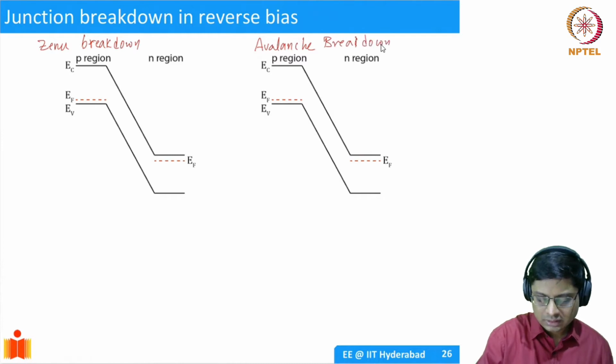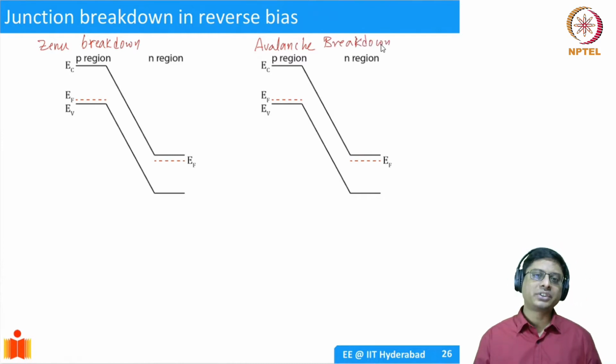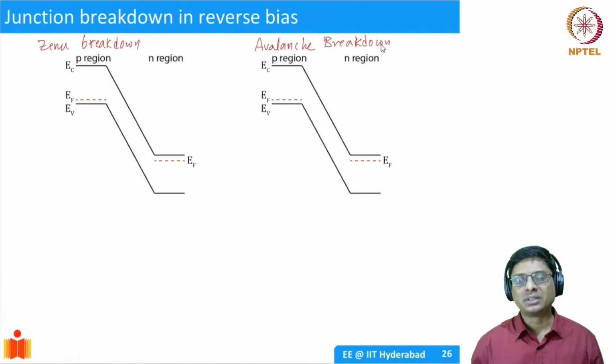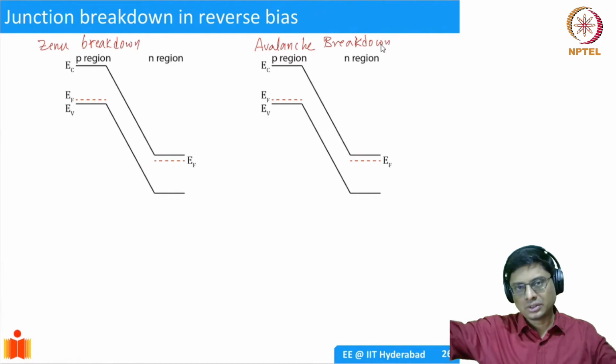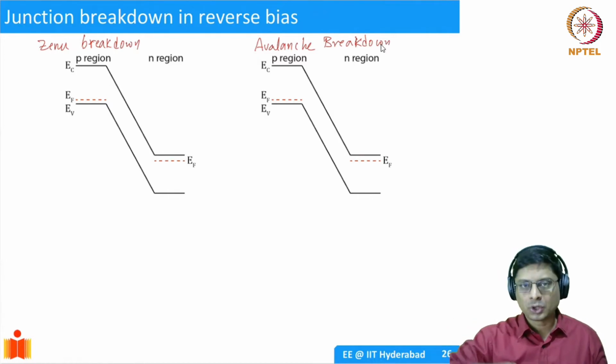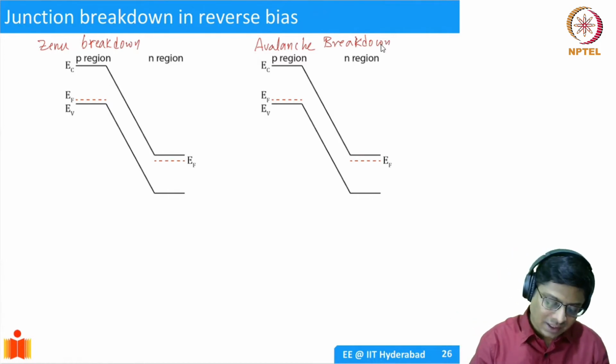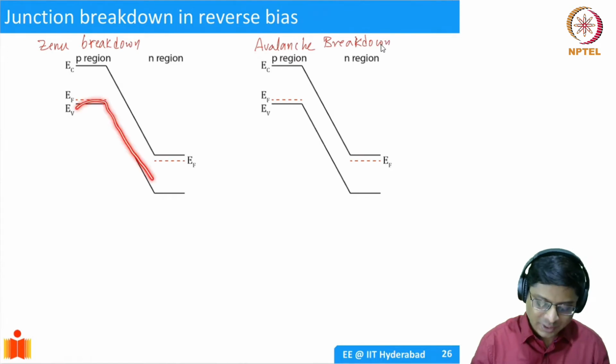In the Zener process, if you increase your depletion width, or apply more and more reverse bias voltage, your bands are going to become steep because you're going to have a larger and larger electric field. There is more charge uncovered, so a larger peak electric field and more band bending. So the bands will bend, and this is a schematic illustration of how the bands could bend.